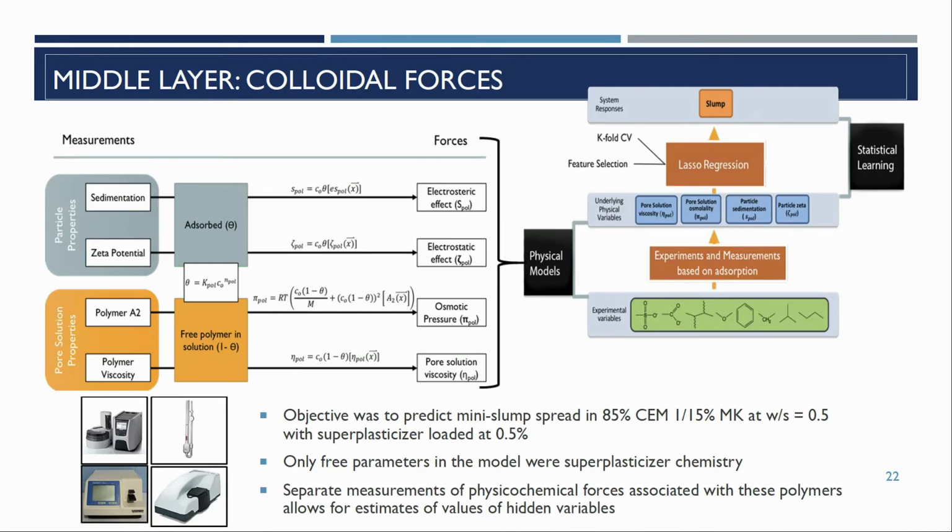So on the right here is sort of how, and hopefully you're starting to get the hang of how, these diagrams work. The output I'm trying to measure is slump. In the studies that we started here, this was just a blend of a type 1 cement with 15% metakaolin, constant amount of water, and constant loading of superplasticizer, so that every sample had these constant. And so even though the experimental variables included cement, it never changed, and so I can just keep it out